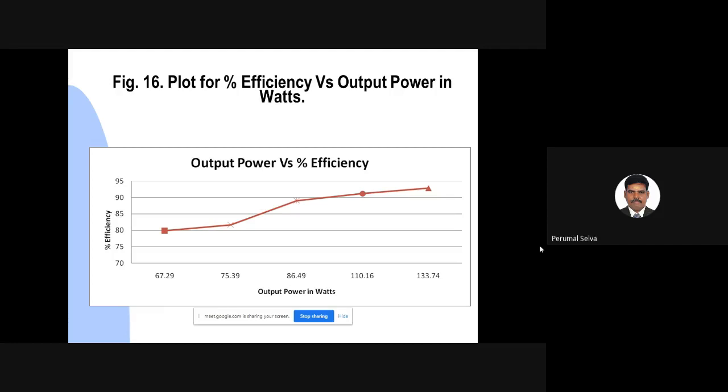Experimental results show that the fuzzy controller based LCL resonant converter is more robust against input voltage and load resistance variations than the PI controller. In conclusion, the fuzzy controller can achieve better performance than the PI controller. Thus, the fuzzy controller design method is highly suitable for application in the LCL DC to DC resonant converter.